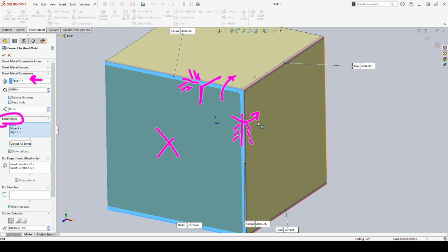And in order for that to be true, this piece right here needs to be a gap, meaning that this piece and this piece can't be the same. They can't be connected right here. There can't be a physical connection there because the sheet metal couldn't physically be made like that. There's no way to bend this guy over like so and this guy over like so and have these already connected in some way and bent over like that. So let's get rid of all that drawing.